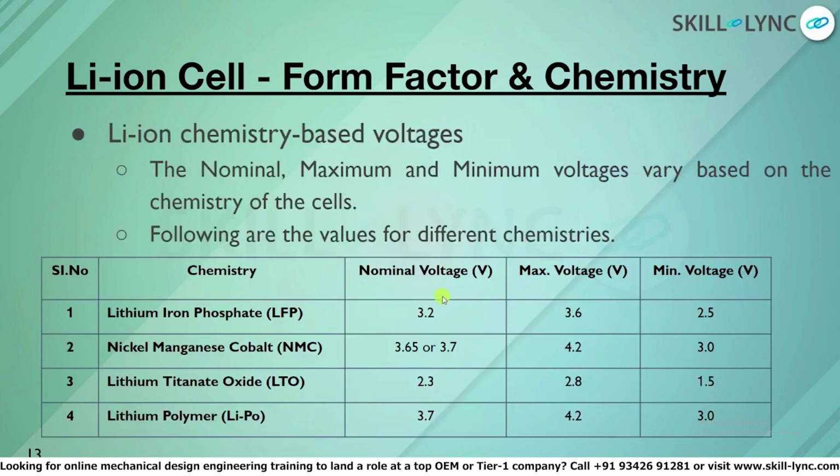Now we would enter into lithium-ion voltage chemistries, for different voltages and its chemistries, etc. So the whole lithium-ion voltage window is divided into three different types. We have a nominal voltage, which is also called open circuit voltage, which is like when a positive and a negative electrode are put together, there is a certain potential which happens to be there, which tends to give a nominal voltage, also called open circuit voltage.